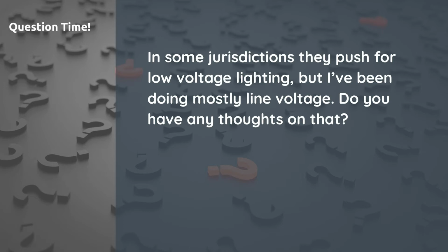Line voltage does have its constraints, where we get a little bit more flexible on the low voltage, especially with LEDs. Again, I don't have to go as deep with conduit. I don't have to go as deep with wire, and my price point is a lot lower on the low voltage side than it is on the line voltage. So it helps me save budget, so that I don't have to start putting in smaller caliper trees or smaller shrubs. I can save that budget on lighting and put it back into my landscapes.